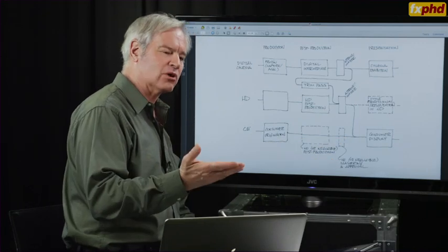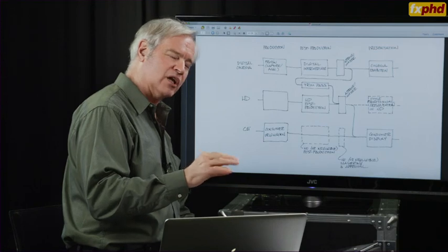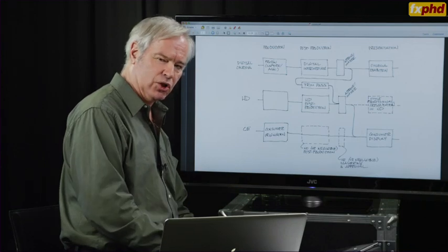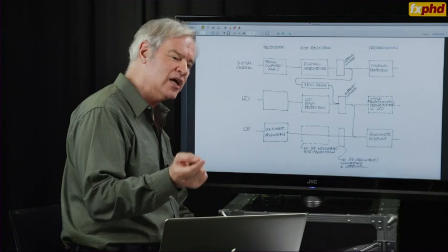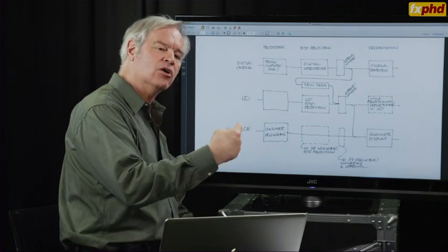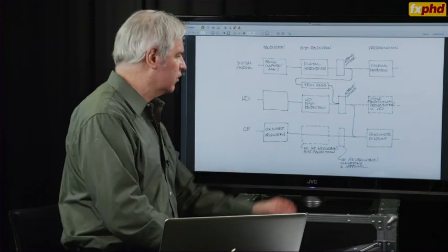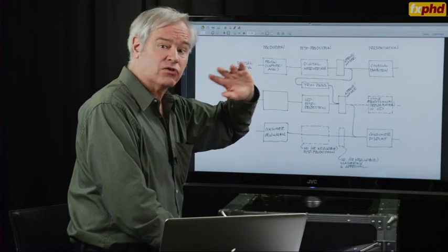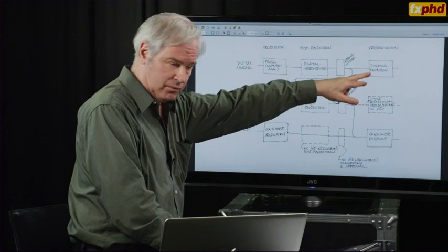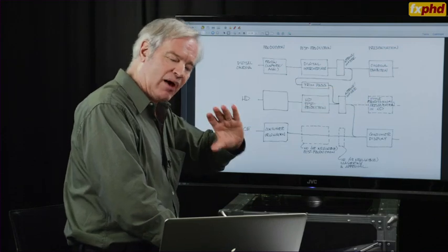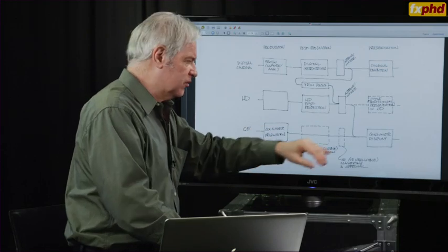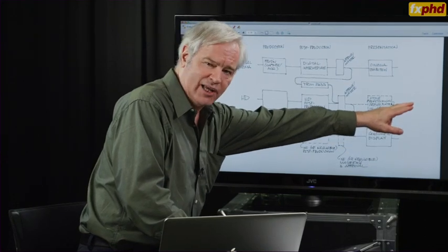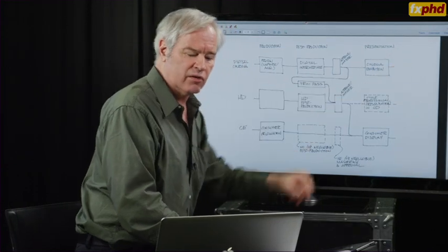And in consumer electronics, well, there's no real standard for that, but 2.2 would be a very typical number for a consumer TV in a consumer class viewing environment. So not nearly as dark as an HD mastering suite, and certainly not as dark as a cinema. So basically the gamma situation is 2.2 for consumers and commodity computing, 2.4 for HD mastering, and 2.6 for cinema.